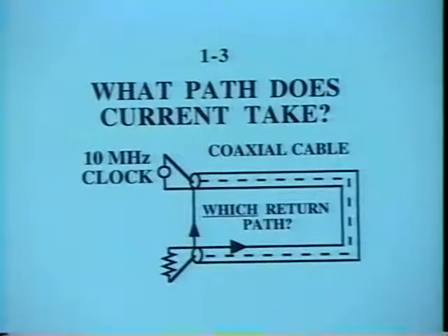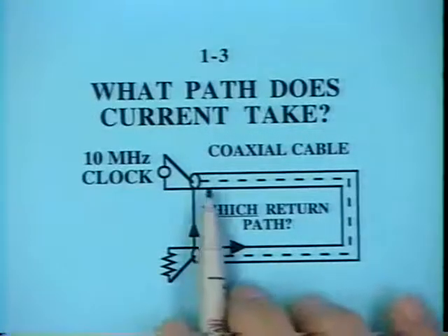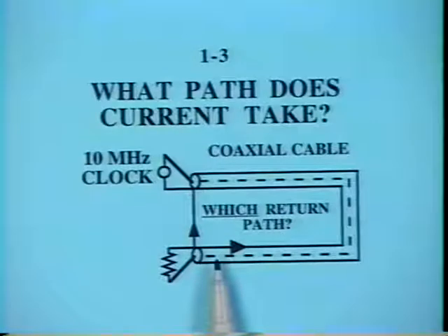In a moment we're going to do a demonstration using this coaxial cable, but for right now we'll just talk about the situation and what we think is going to happen when we do that demonstration. Imagine a piece of coaxial cable about 3 feet long. The dotted line represents the center conductor inside the coax. The solid lines are the outer conductor. We have a load resistor on one end. That resistor, along with the source, determines the amount of current that will flow on this cable.